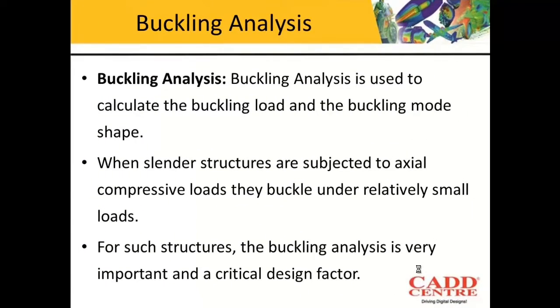Next we will talk about buckling analysis. Buckling analysis is used to calculate the buckling load or the buckling mode shape of a structure. What kind of structures do we need to study over here? Whenever there is a slender object, meaning any object whose length is very long compared to the cross section of the body, that is a slender structure.